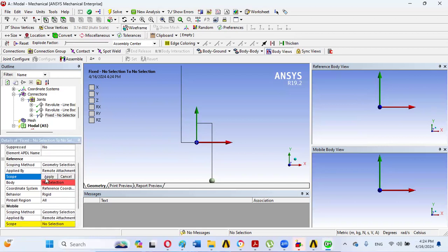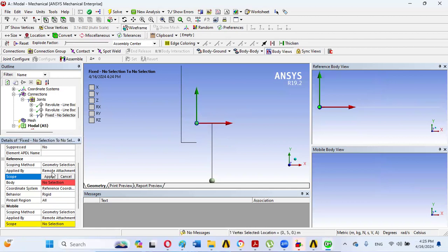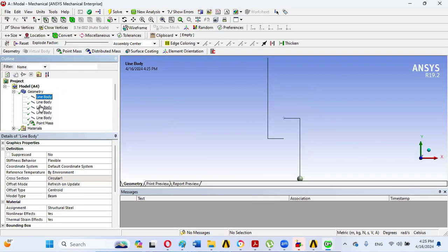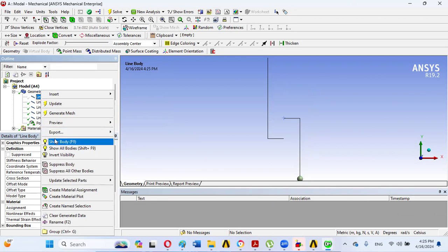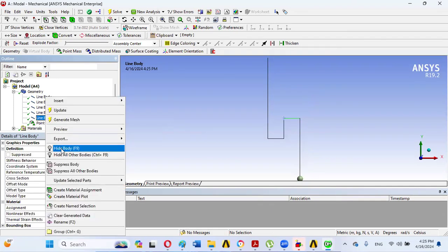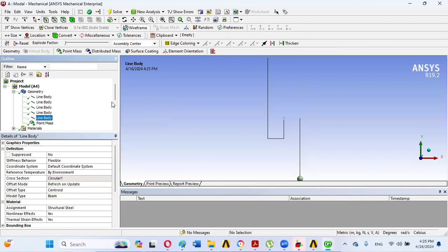For example, in the reference point we can use this location here, and we can click on apply, and after that we can make the central portion of the cable visible, and then we can make it of this right diameter of the pulley, and in this way